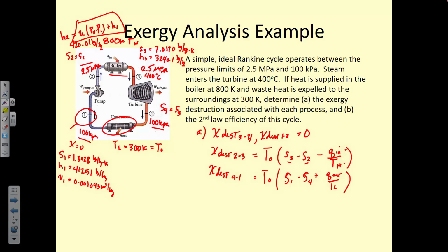If it's a much higher pressure, like 10 megapascals, you can look in table A7 in the book. In your homework, I think it's higher. Okay, state 4, we know S4 is equal to S3, so then we end up having to calculate a quality of 0.944, and our H value is 2548.59.